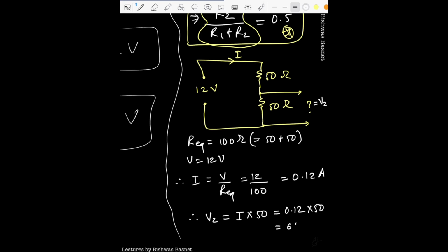And this is how we got 6 volts here using 50 ohm resistors, right? But we can use other values of resistor as well. But the only constraint here in the practical case would be how much current is flowing through the circuit, or let's say what's allowable there.